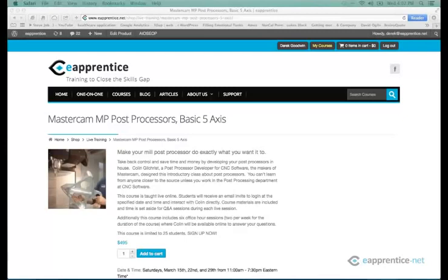I would say that you need to buy a customized post processor for that machine. Okay. So as far as I know, we don't have any generic 5-axis post processors that also have lathe capabilities. There are certainly plenty of vendors out in the marketplace that have posts that will support that machine, but you're going to have to go specifically to them.